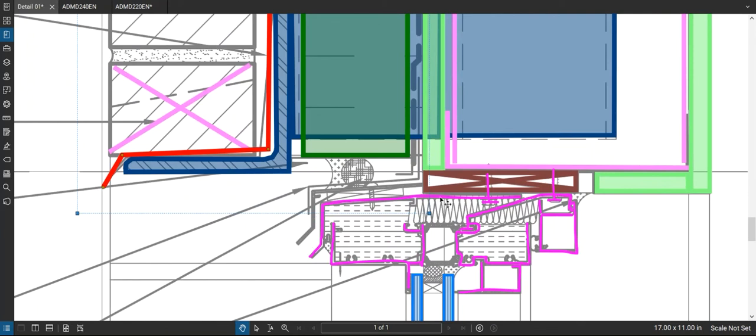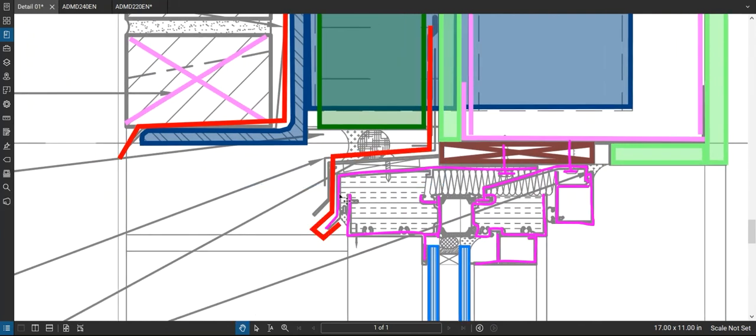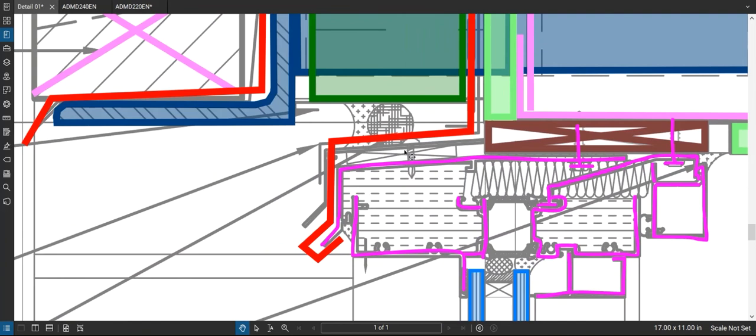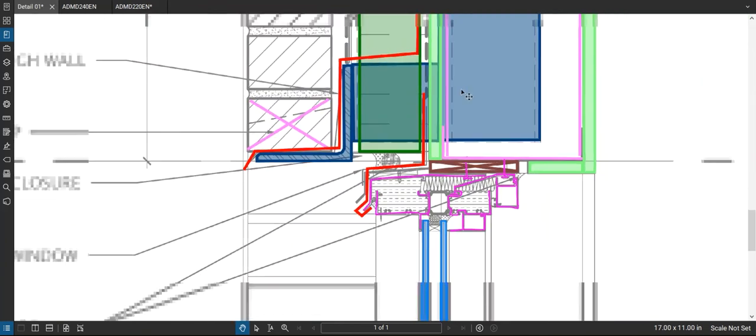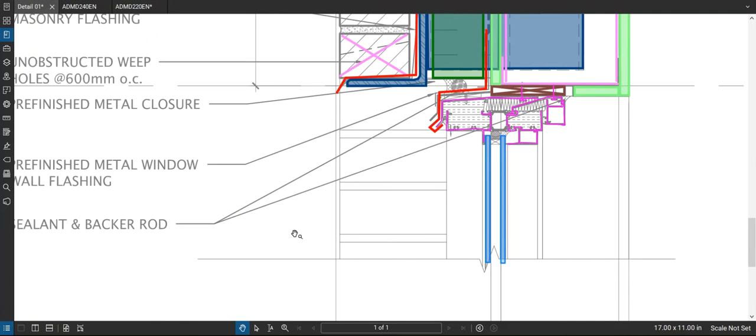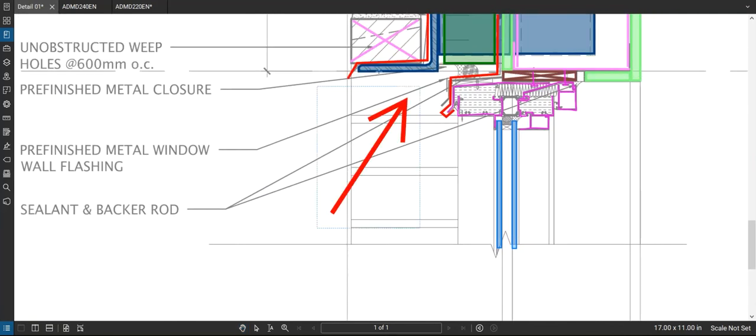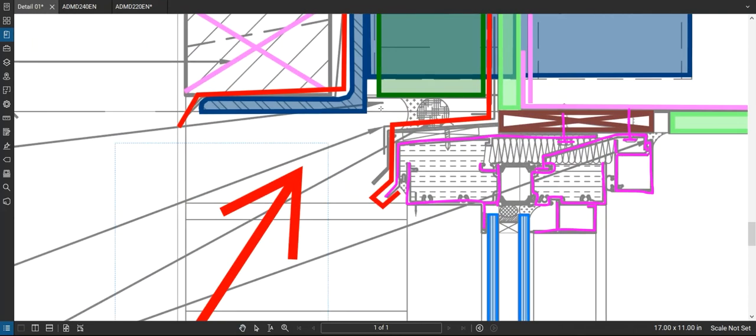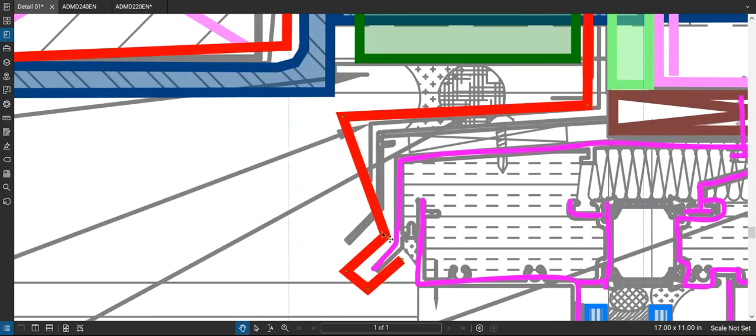Next, we've got some more flashing here to deal with. I'm a little confused by all the goings on here, but anyways, you'd have some flashing here. And again, just always picture yourself looking up at this. What am I seeing when I look up here? Do I want to see the underside of the steel angle? It's very common to leave it exposed. I suppose it could be stainless steel, but that wouldn't be very common. You could paint it. But you don't want big gaps like this either, so you want to make sure that spaces like that are discreet. Let's put it that way.